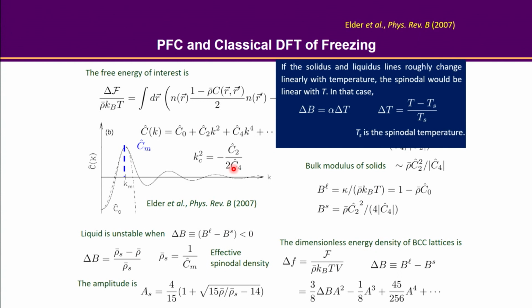So it is impossible for the PFC to capture all the physics, but depending on the physics you would like to include, you can say which parameters are important in your material problem. Then you can select those parameters that are crucial, and you want the PFC to capture those terms. Then you can do a parameter fitting to determine the proper phase field crystal parameters you should be using.